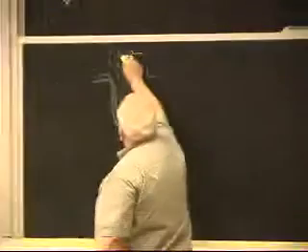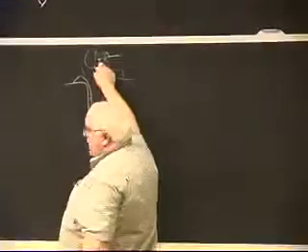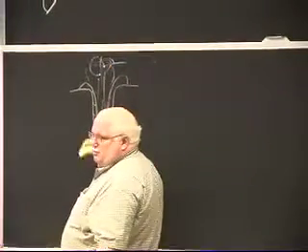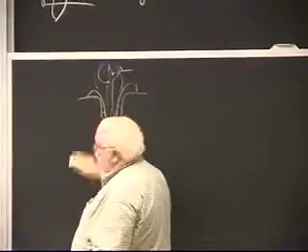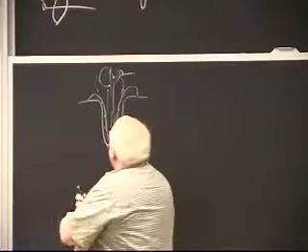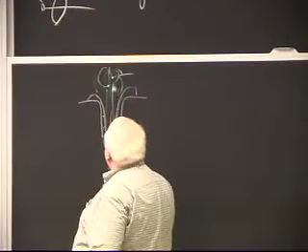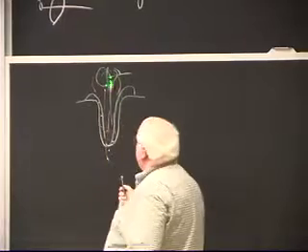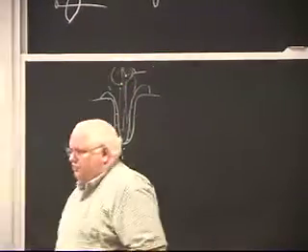The electrons penetrate the metal vapor in the cavity. By that I mean you have a tremendous amount of metal vapor that forms up here because of this high intensity beam. In fact, it's the vapor shooting out of here that drills the hole. So you've got metal vapors up here, but the electrons having 40 kilovolts of energy just punch right through that. That's a very rarefied vapor, particularly if you're in a vacuum. It's essentially a low pressure vapor, and the electrons just penetrate right through as if it wasn't there.